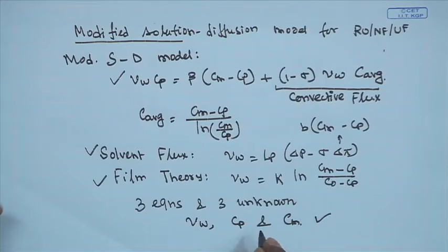Okay. So, these are the various variants of the solution diffusion model to get the system performance in a very predictive mode. Only some of the parameters like Lp, real retention, and B, which is basically the solution constant for the solution diffusion model, have to be estimated separately by conducting a separate set of experiments. Once these are done, if you know the operating conditions, the transport coefficients, the geometry and the solution properties, then one can have the system performance in a predictive mode.